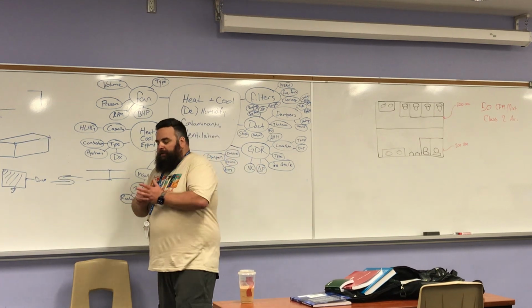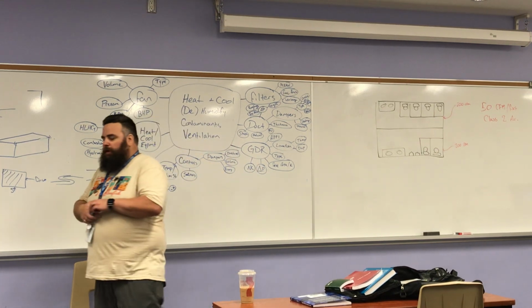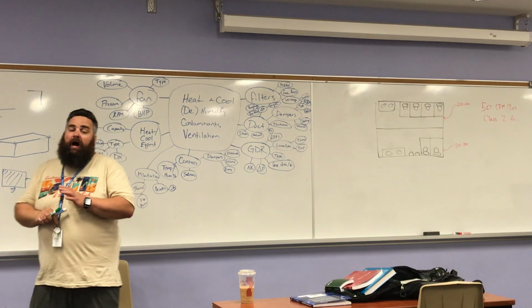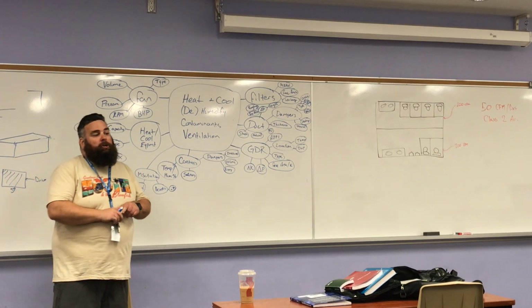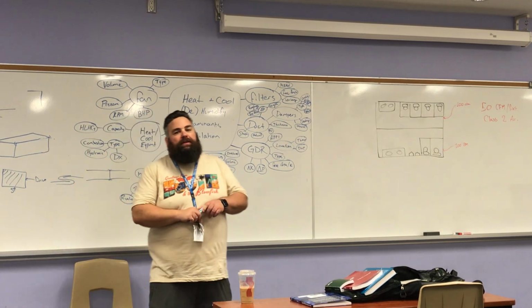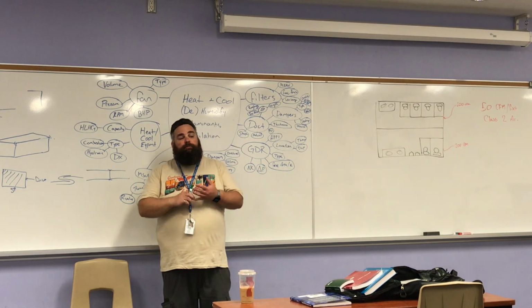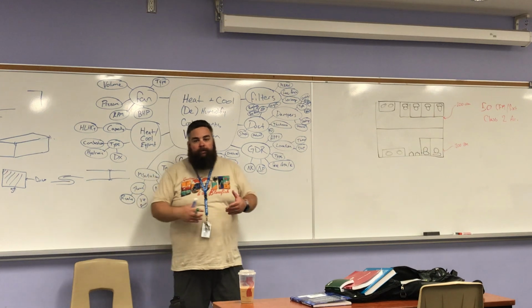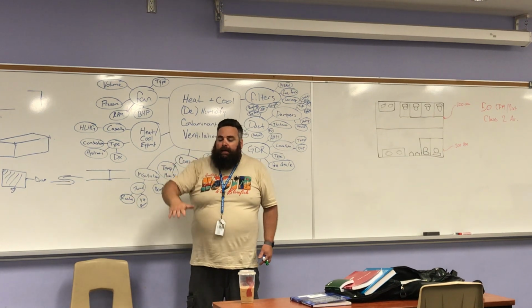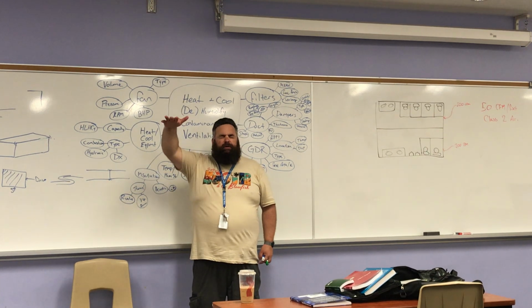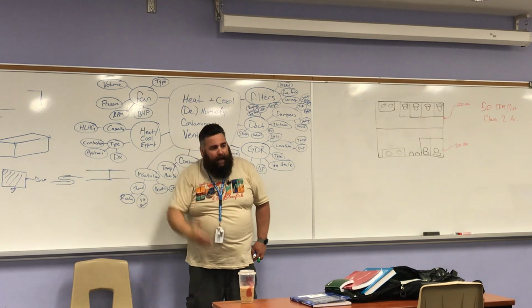So linear bar grills, the last time I used one would have been this high-end custom home in Richmond Hill, where what I was after was a really good throw or curtain of air coming down. We actually had a stairwell that went up 3 stories and was all glass.